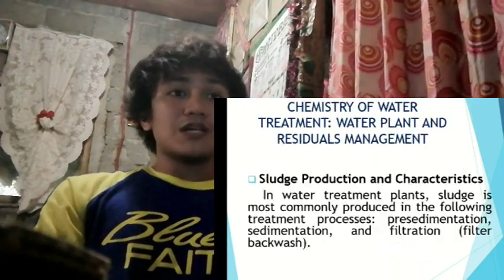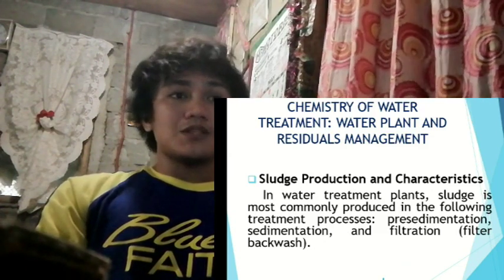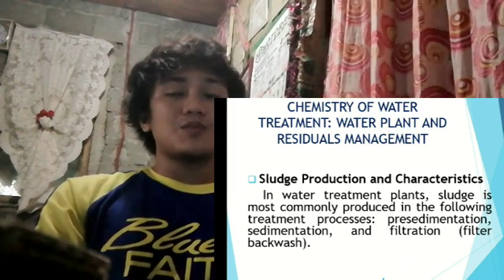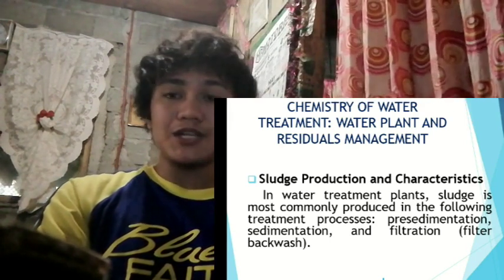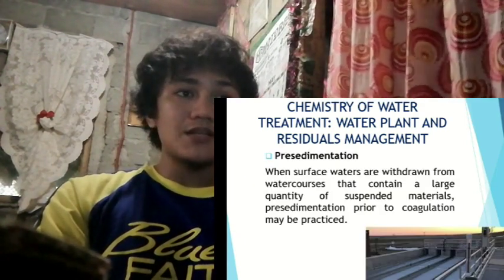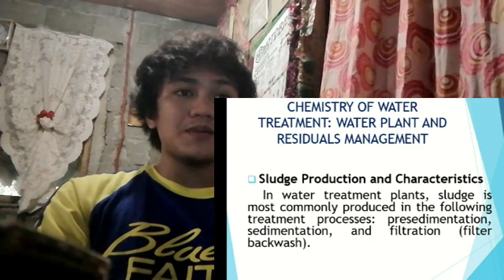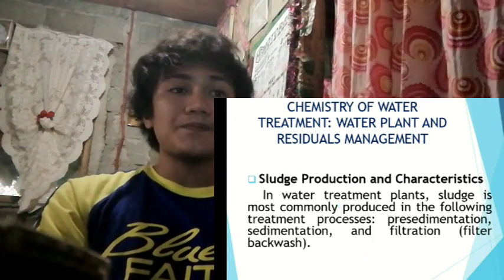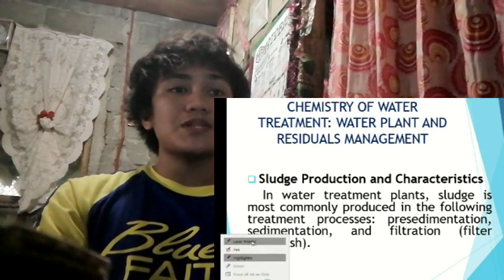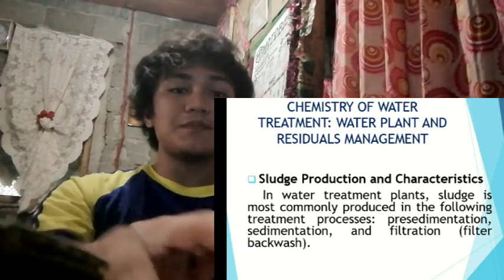The most logical sludge management program attempts to use the following approach in disposing of the sludge. First is the minimization of sludge generation. Second, the chemical recovery of precipitates. Third, sludge treatment to reduce volume. Fourth, ultimate disposal in an environmentally safe manner.